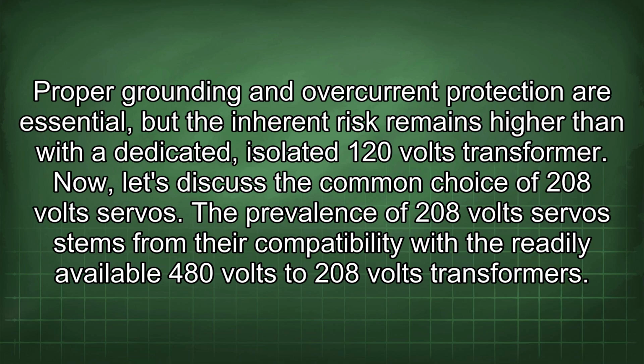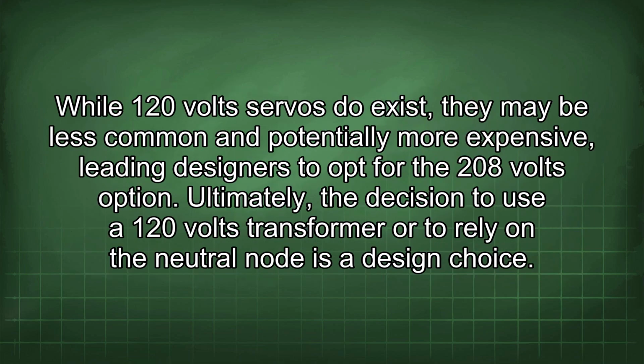Now let's discuss the common choice of 208 volt servos. The prevalence of 208 volt servos stems from their compatibility with the readily available 480 volts to 208 volts transformers. While 120 volt servos do exist, they may be less common and potentially more expensive, leading designers to opt for the 208 volts option.